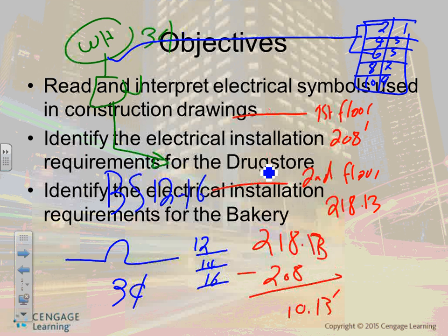So they have a generator required. If you have an elevator, you're required to back it up, as well as an emergency light. So they're backing up the elevator control and equipment with the generator. On a loss of power, it automatically starts the generator, picks up, and your elevator is up and running. Once power returns, it shifts you back to the normal power. So once power goes, it switches over, yes, within 10 seconds.